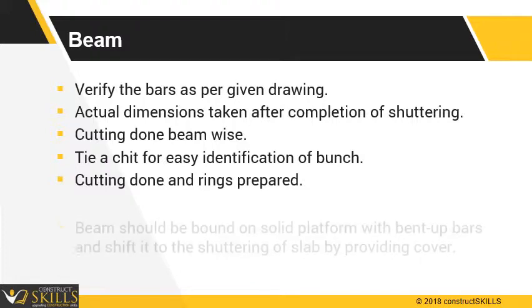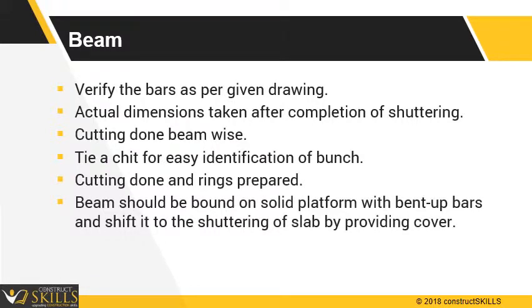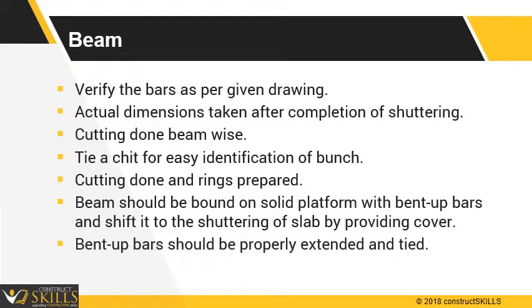The beam should be bound on a solid platform, along with bent-up bars, and shifted to the shuttering of the slab by providing proper cover. For continuous beams, bent-up bars should be properly extended and tied by binding wire.